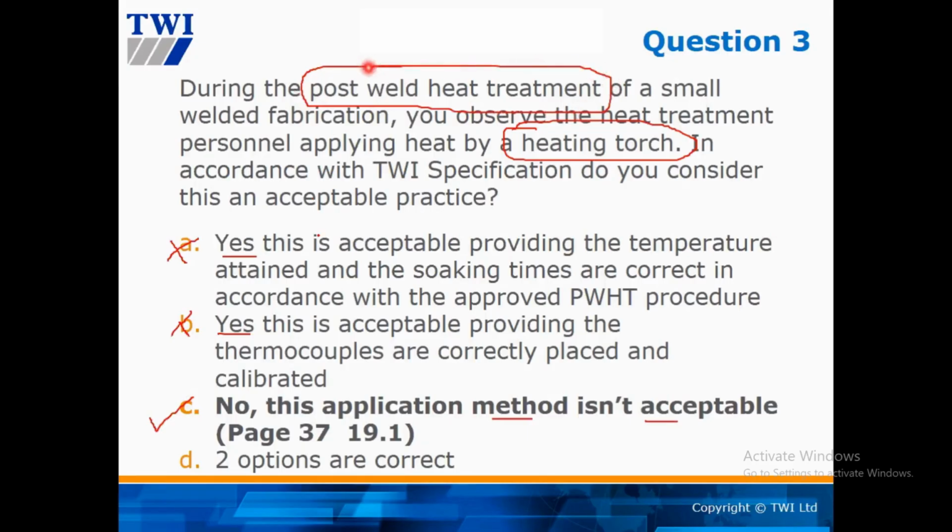But if you want to use a heating torch or something for preheat, you need to check from the WPS. In real life, check from the WPS. But in these questions, they ask for post-weld heat treatment, PWHT. For post-weld heat treatment, from our spec, it mentioned only 2 choices, by using furnace or maybe using heating blanket.